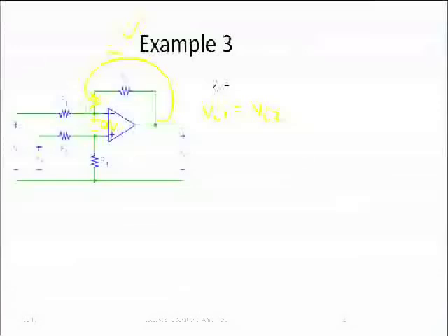All right. So now, what is Vi? Of course, we don't know Vi1 and we don't know Vi2. But could you figure out one of them? Okay. Vi2 is a voltage divider. So Vi2 is equal to Va times R4 over R3 plus R4. Now remember, I told you voltage dividers, we'll use them all the time. If you need to think hard about the voltage divider, then you really need to spend an afternoon or an hour or so thinking it through once and for all.